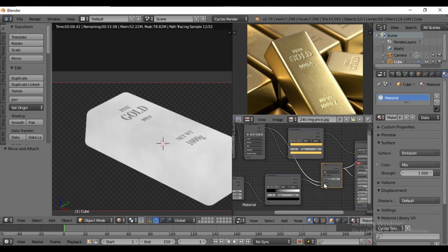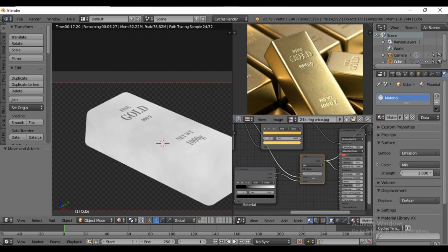First, check the factor. Set the factor to 1, and it indicates only the noise. Again, change the factor to 0, and it indicates only the letters. However, we require a higher level of noise, so setting the factor to 0.8 is ideal for our needs.